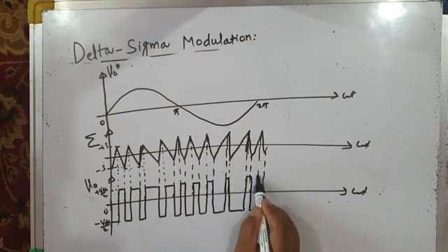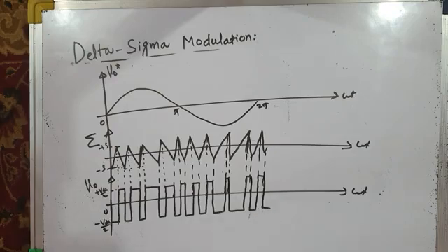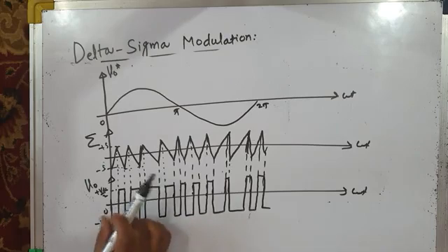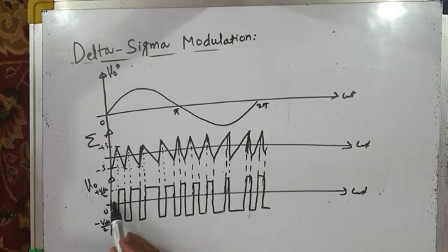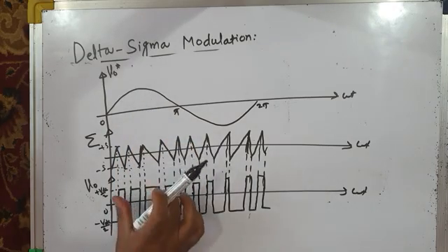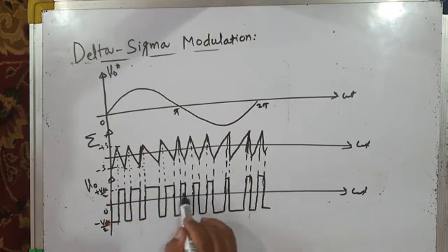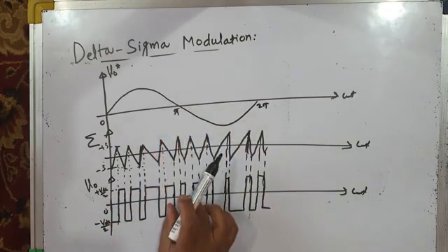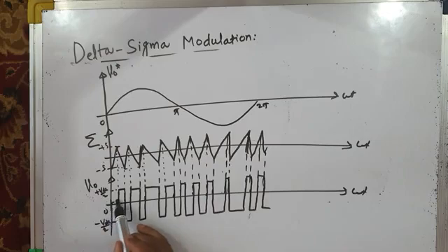This is how your load voltage varies. You can very interestingly see, if you take the instantaneous average value of this pole voltage, the average value of this is small. Then as you move towards the peak, you can see the widths of pulses increase. And as you go towards the corners, the widths of pulses decrease. So the instantaneous average pole voltage will be sinusoidally varying like this.